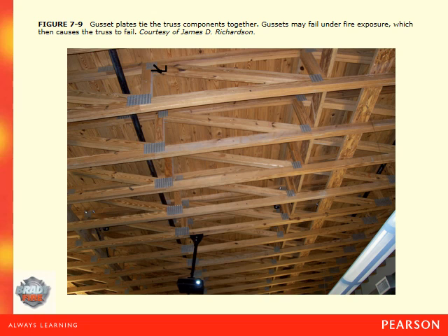However, if we had a fire and say that fire weakened that area right there, causing the gusset plate to fail at 1000 degrees, then the entire roof system could collapse because its integrity comes from the whole structure and not just individual sections, as one continuous structure, if that makes sense. So essentially you're only as strong as your weakest link, and if one link fails, then the whole system will fail, is a great way to put it.